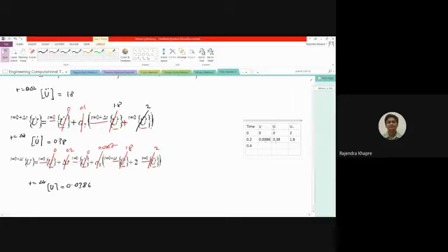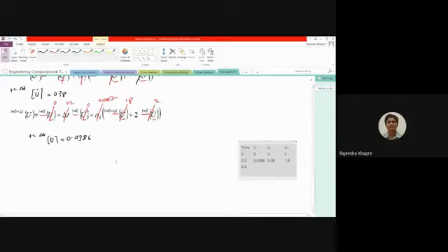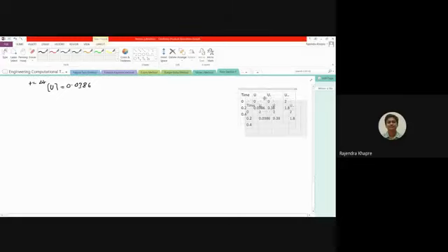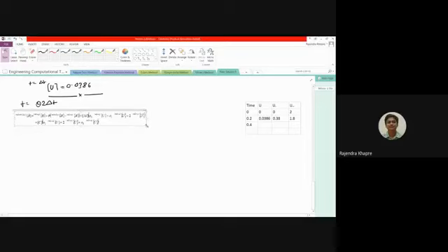Now you can use similar equations for calculation of the response for the remaining steps. Let me write down the expression for you so that you can solve them. The very first expression is the calculation of the effective load vector. Now I am working on time as theta times 2 delta t, because you won't be getting the values directly at 2 times delta t. So the equation is going to give you the values at theta into 2 times delta t.